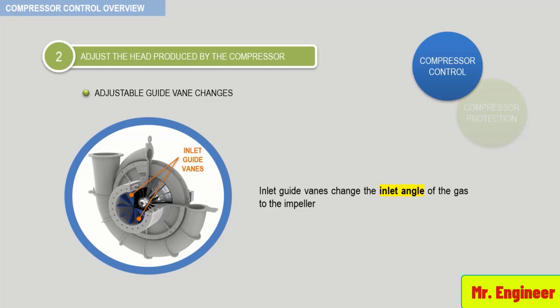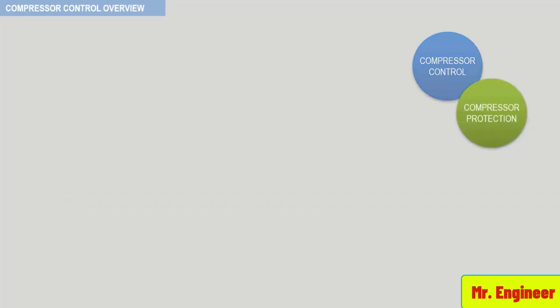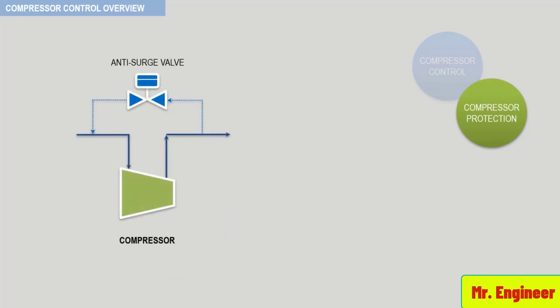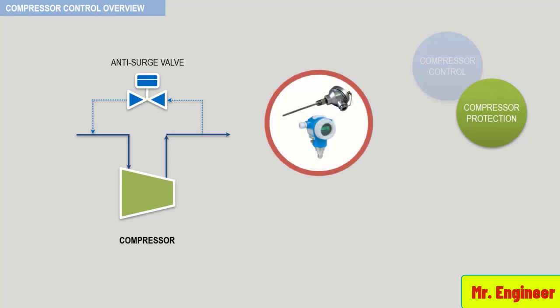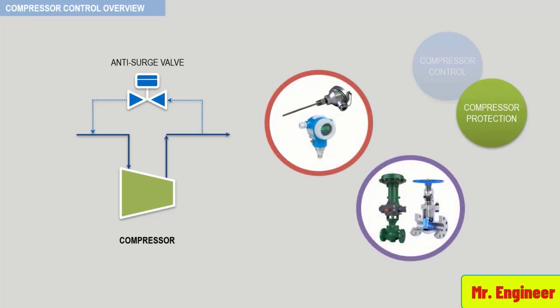In this section, we will also cover the compressor protection systems. The basics of surge protection will be presented, and the following facts will be reviewed. The overall concept of a surge control system is to reduce the system resistance, and thus prevent low velocities in the impeller. The concept of the surge control system will be discussed, and the important fact of coordinating all components will be covered. All instrumentation, controllers and associated valves must be properly sized to enable the system to work efficiently.